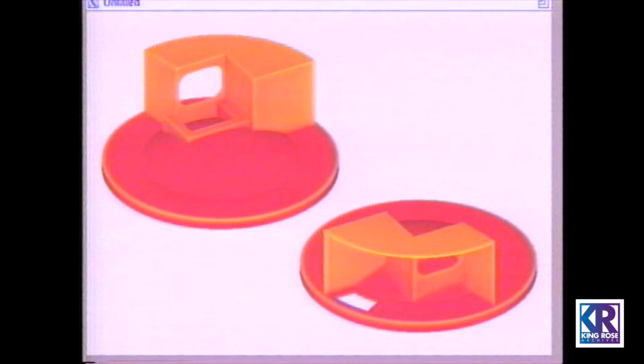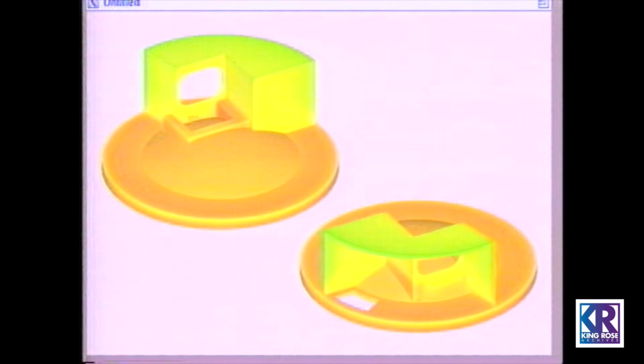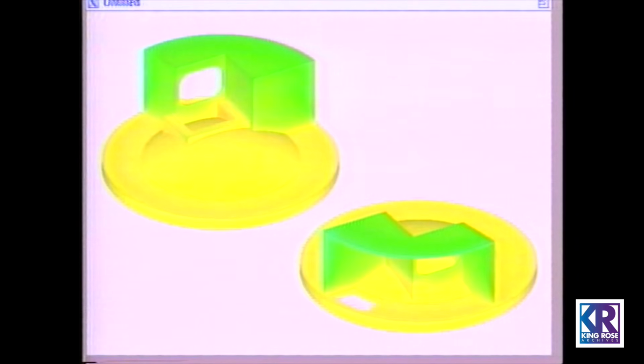The part illustrated here is shown starting at 2900 degrees Fahrenheit and allowed to cool to 1570 degrees Fahrenheit by radiative processes. This thermal model includes the effect of view factors, or the effect of one section of the part radiating heat to adjoining surfaces. With view factors, areas such as pockets remain hotter than would be predicted without their incorporation.